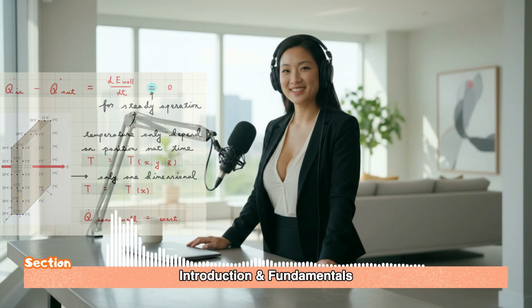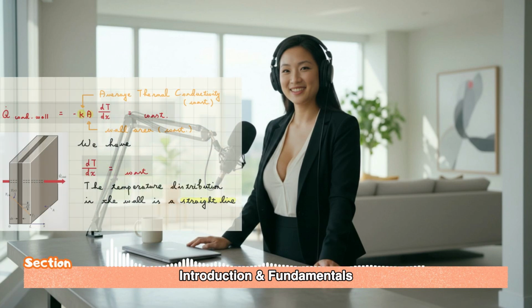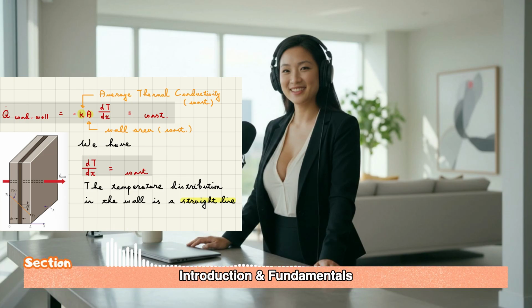Yes, and this result is probably the most elegant way to visualize steady, one-dimensional heat flow. The temperature distribution through that wall is not a curve. It's a straight line. The temperature just varies linearly with distance x, and that linear profile is the visual proof that the rate of heat flow is constant at every single point in the material.